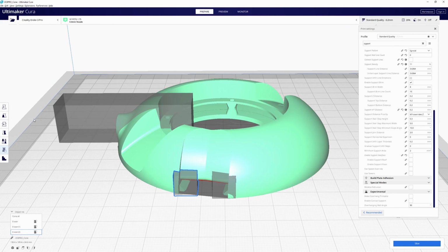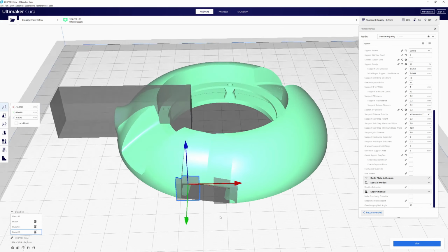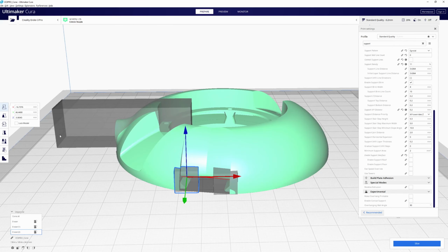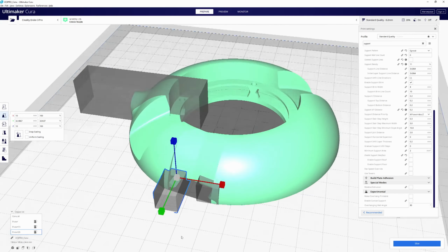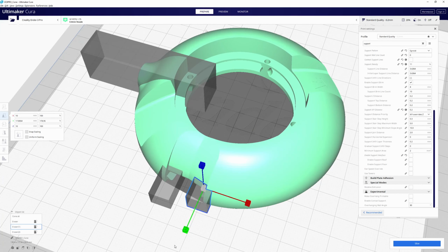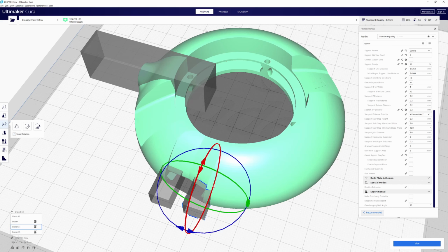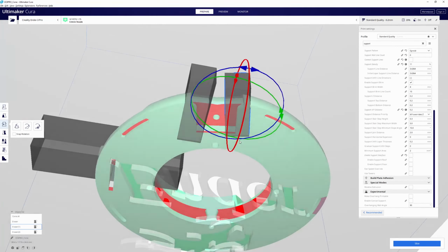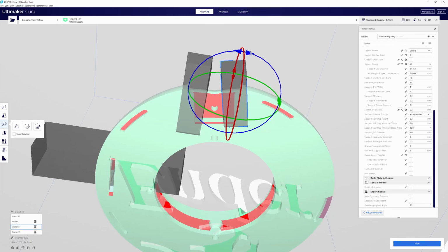So, like I say, Cura is really good at doing a scale and then a rotate. So if I want to scale this one, make it longer, which we're going to need under here, I'll do it to this one as well. That's all fine, and it's better to do that first, because if you rotate it, I find this a little bit frustrating. We're going to uncheck that snap rotation here so that we can get this a little bit more parallel with where our support clamp is.